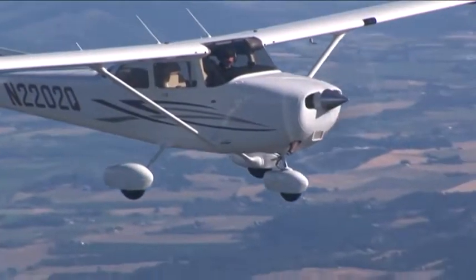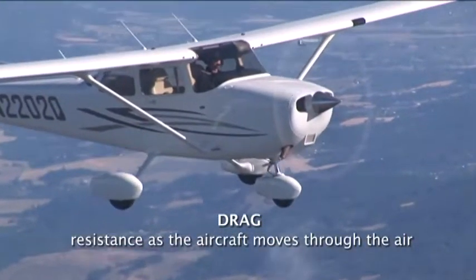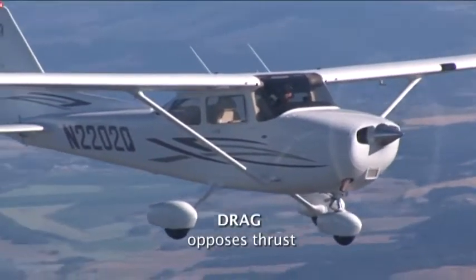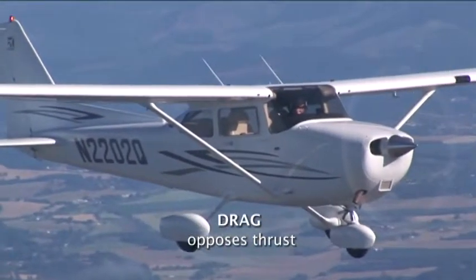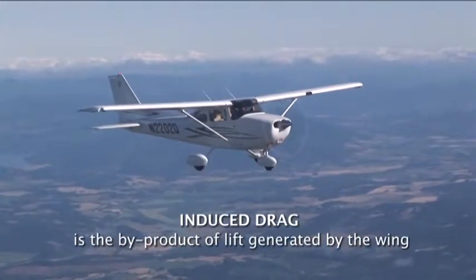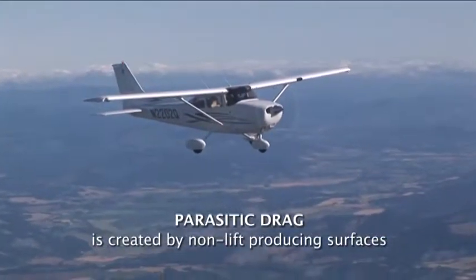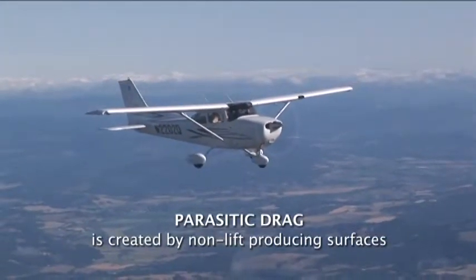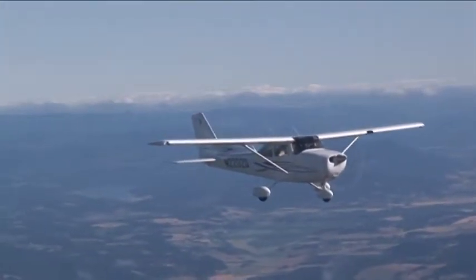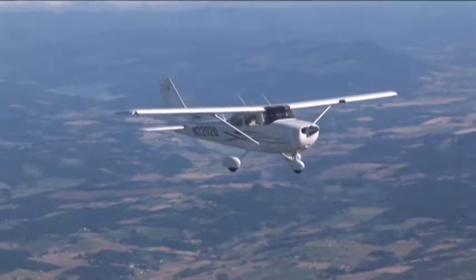The final force acting on an airplane is drag. Drag is the resistance of an airplane as it experiences motion through the air. Drag opposes thrust. There are two types of drag, induced and parasitic drag. Now, induced drag is the necessary byproduct of lift generated by the wings. Parasitic drag is caused by non-lift producing surfaces such as the struts, the landing gear, the tail, and the fuselage impeding air molecules as the aircraft moves through the air. Both induced and parasitic drag oppose thrust and slow the airplane down.